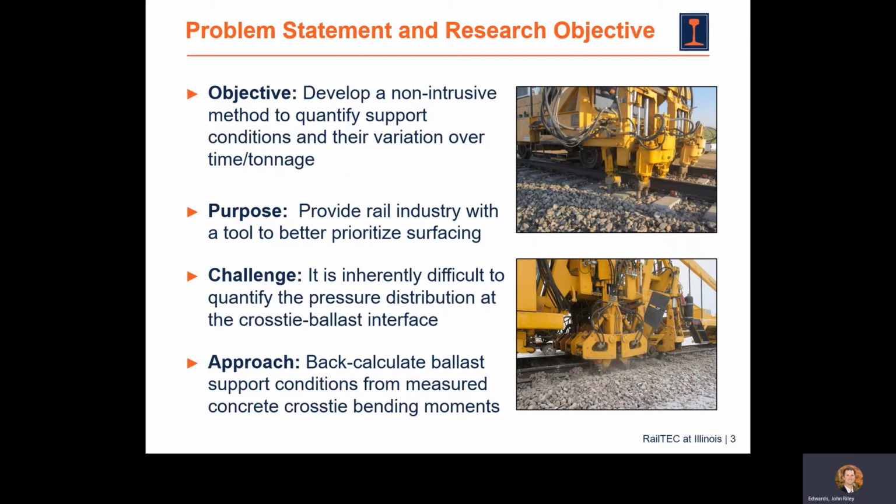And specifically in terms of surfacing, we know that surfacing ties up a lot of valuable track capacity, and if we could lengthen these surfacing intervals without it being to the detriment of our tie's health, that would be advantageous to our industry. The challenge, as I said earlier, is it's inherently difficult to quantify the pressure at this interface without manipulating the experimental conditions by inserting some other form of instrumentation.